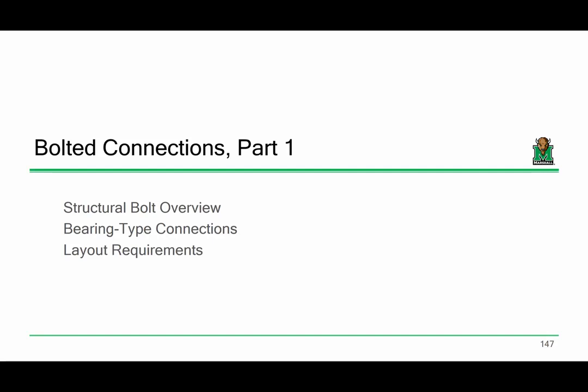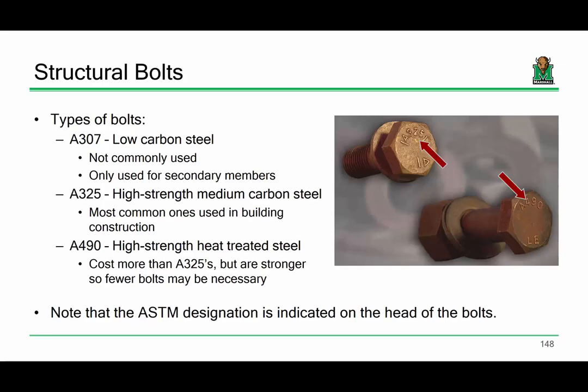The facts are, as a structural engineer, you really never have to deal with them unless you're load rating a bridge where there are rivets installed. If you are, there are guides that help you determine the capacity of a rivet, and usually they're way conservative. So it's usually a lookup, and we can sort of bypass that. You're never going to be doing a new structure with rivets. Let's talk about bolts, okay?